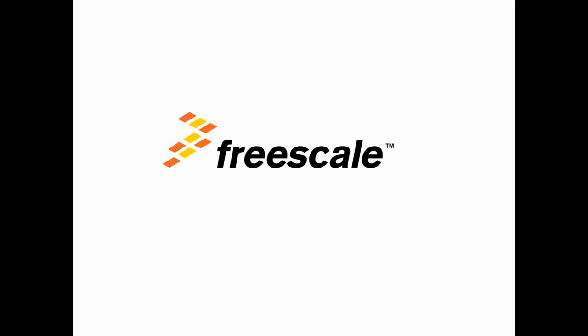Yeah, I have a gut feeling that it's faster, especially the transaction recording gives you immediate feedback on what the test bench thinks happened versus what you see. So you can look into your streams and see what registers got accessed, which didn't. I don't look at the waveforms. I see what ISRs were exercised, what stimulus did run. So this helps immediately to get me into the static mode from design, versus having to set a breakpoint to figure out was this register accessed, or figure out what address is this, and because it's not the whole thing, you have to extend it and so on. So it helps a lot.